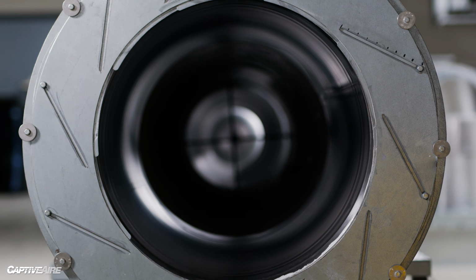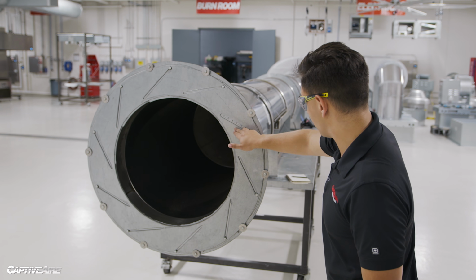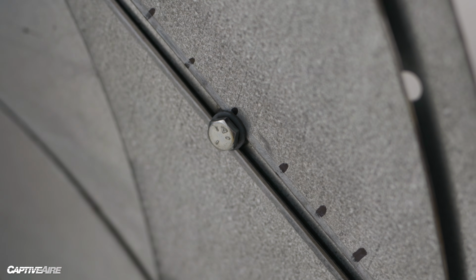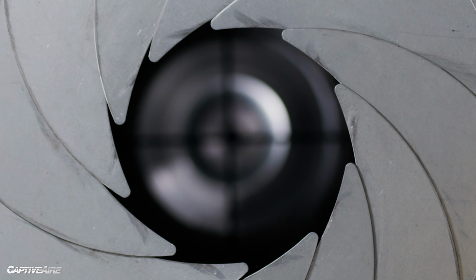Here we have our iris. So we have 10 points set up on our iris, designated by these 10 points marked in marker right here. As we close this iris, we're going to increase the resistance and restriction on the airflow. So we need 10 separate points to get a really accurate fan curve. We're going to close this iris step by step, and that'll build our fan curve.